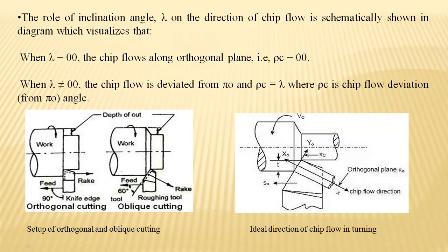And here in the diagram, it's very clear that the orthogonal plane exists within a 90 degree range of cutting, by maintaining the rake angle exactly opposite to the work part. This is the work part which is placed, and exactly by maintaining the perpendicular axis, that is 90 degrees. See here, 90 degrees is being maintained and machining progresses by imparting a feed.